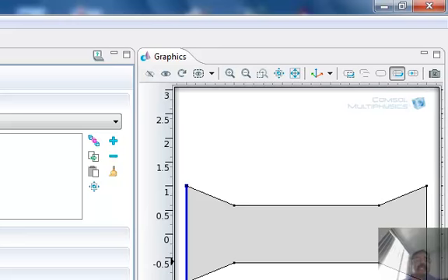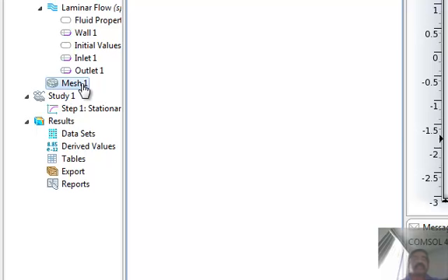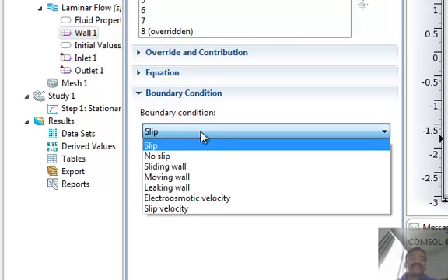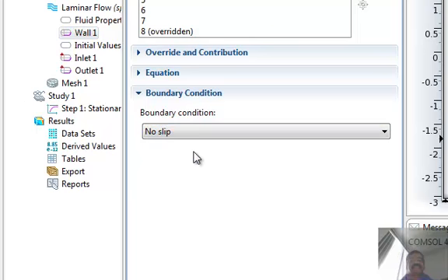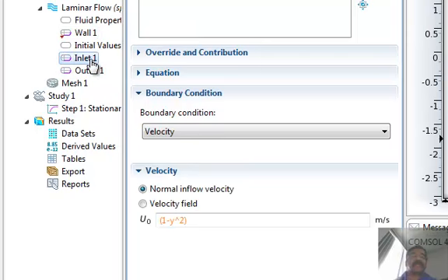All right. So we have set up the inlet, we have set up the outlet. This is something that I need to ask you to accept on faith if you haven't done a numerical methods course. The boundary condition on the wall might have been changed. Did I change that? I don't know. Yes, thank you. All right. And outlet is pressure, inlet is velocity, that's fine.